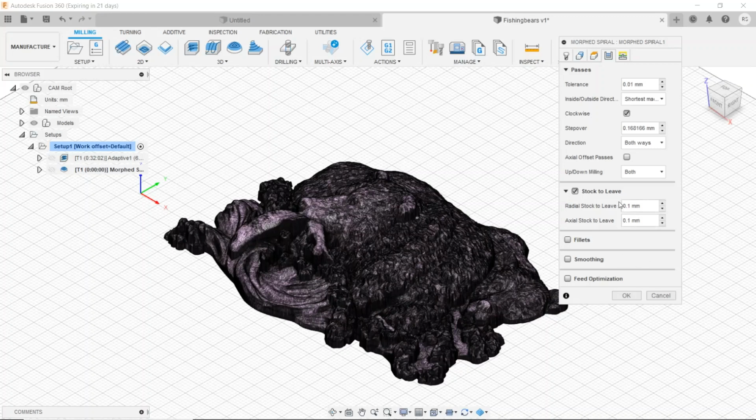And then make sure you leave a little bit here so that when you add another tool path you'll have something to cut away. It's the same thing. And you can just keep stacking tools on here, as many as you want, as long as you keep leaving some material left over for each tool to cut. So based on that knowledge, we'll move on.